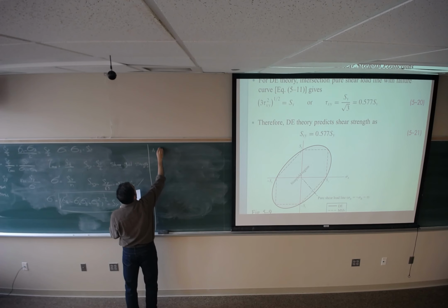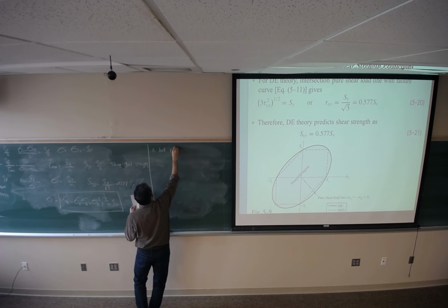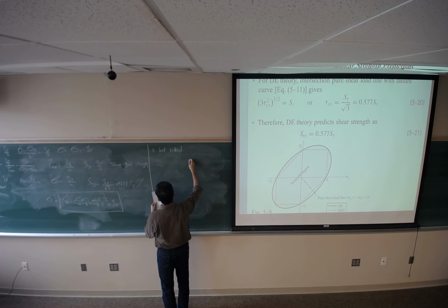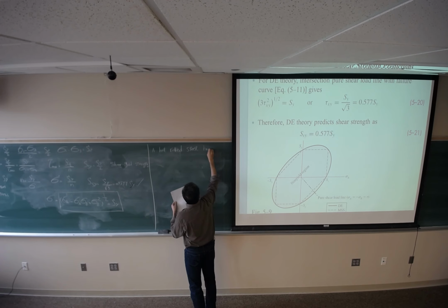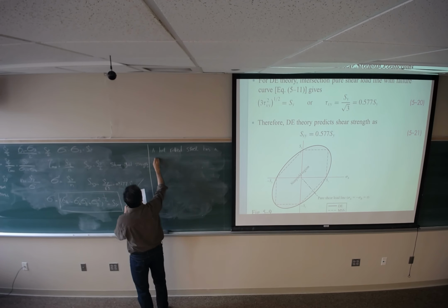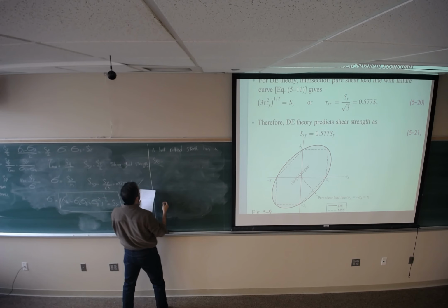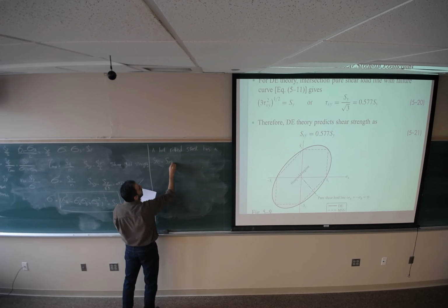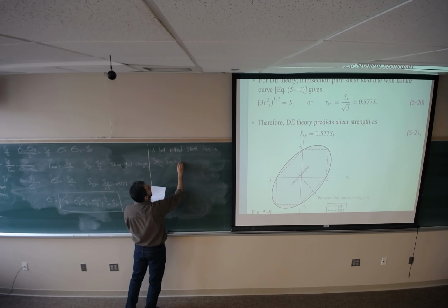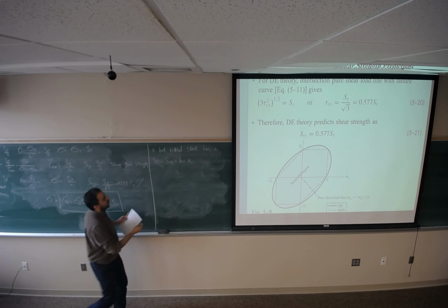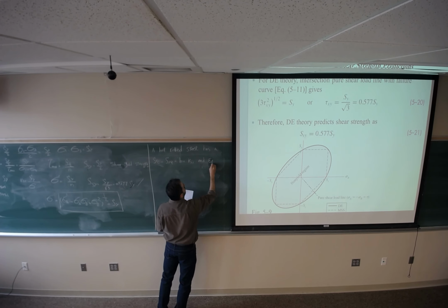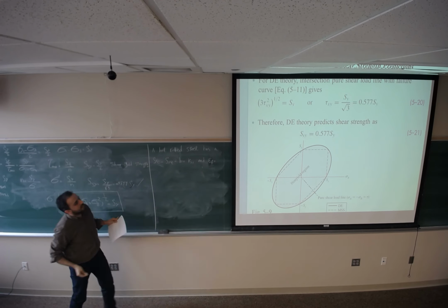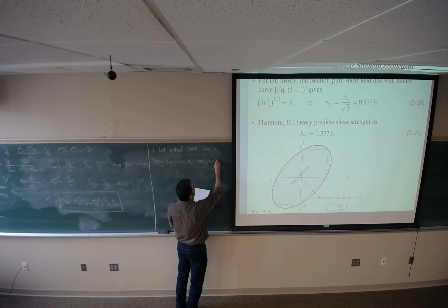A hot rolled steel has a yield strength for compression and for tensile that are the same, 100 kpsi, and a strain at the fracture point of 0.55.